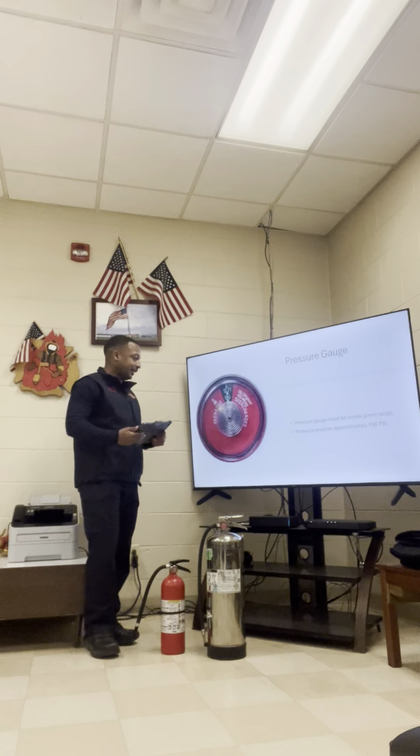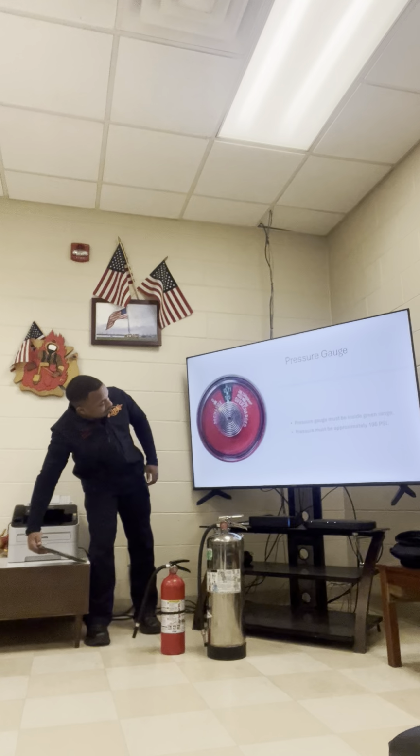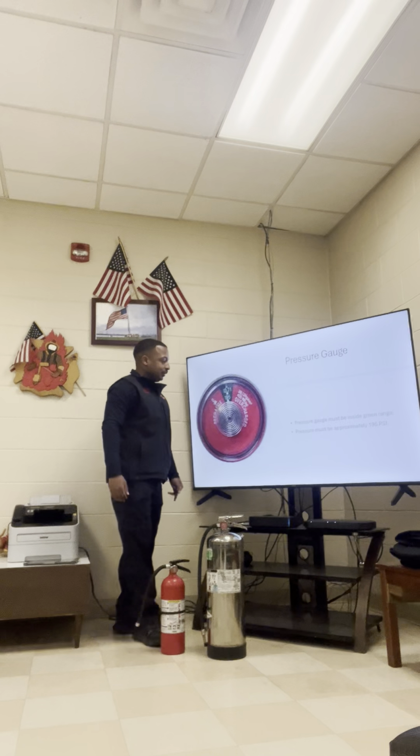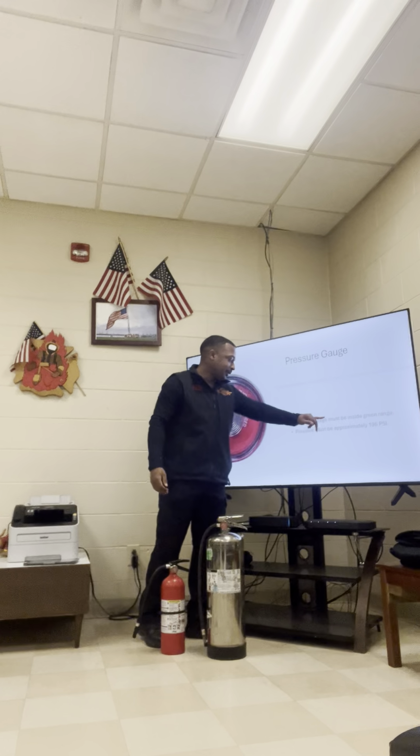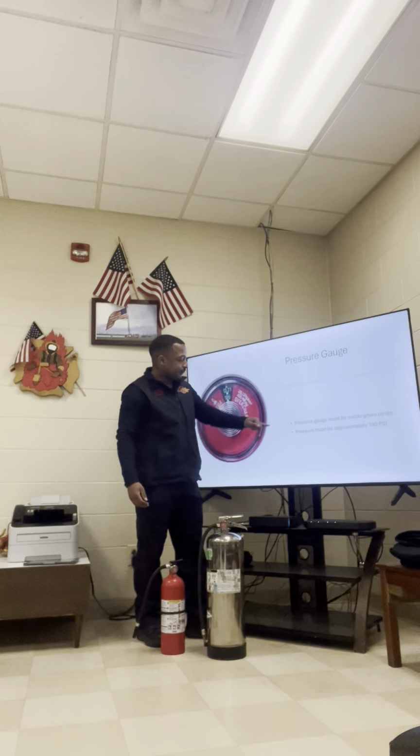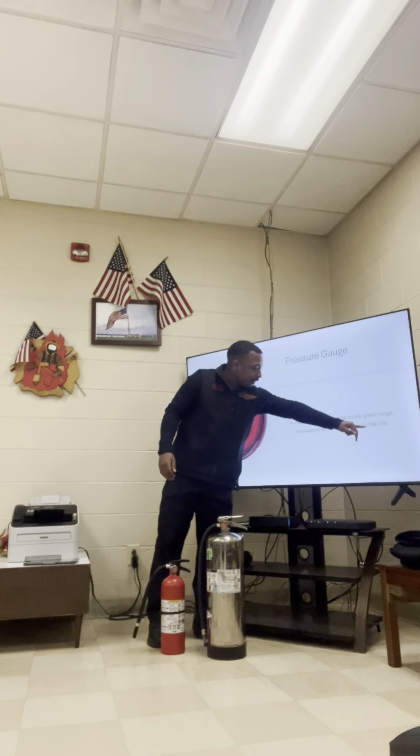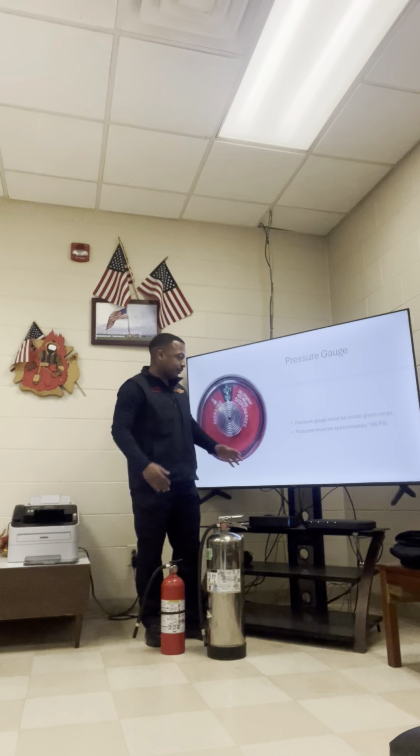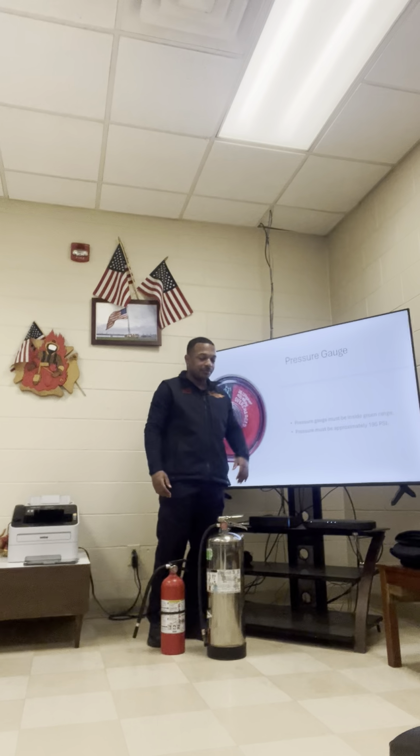Here's a picture of a pressure gauge. The pressure gauge must be inside the green range. Pressure must be approximately 195 psi for most of the common fire extinguishers. Sometimes it can be a little less if it's smaller, but the most common is 195 psi.